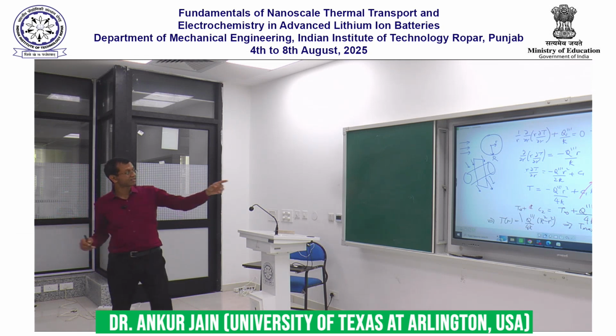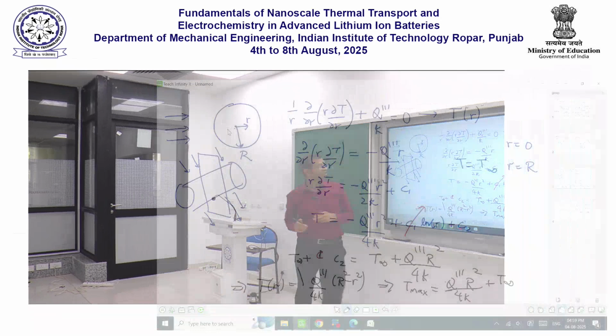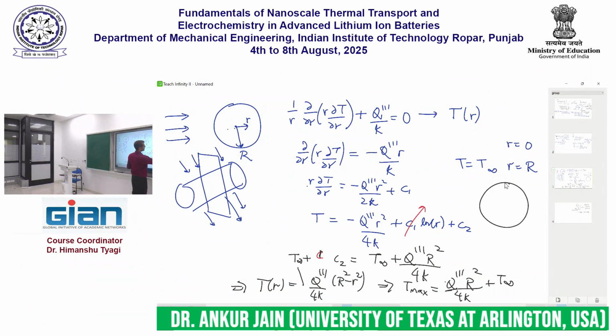By the way, I said that the biggest problem happens at the center of the cell, and one very straightforward way of solving that problem is to build a cell with a hole and blow some air through the hole. That way, you will be cooling. Convective heat exchange mechanism. There will be a hole in the center. No, I'm talking about a single cell. This is just one cell, and I have a hole through the cell where heat exchange can happen. I can blow some air exactly through this channel down the cell, and I can remove heat from the very core of the cell. Internal surface also.